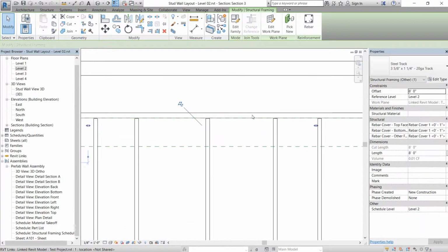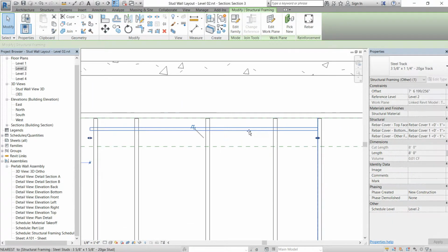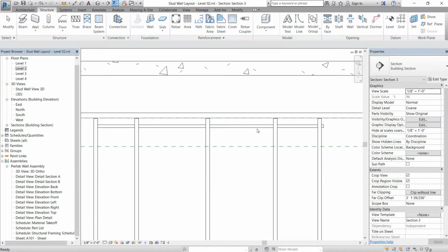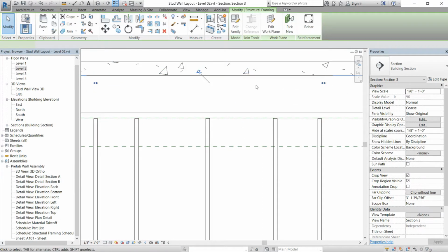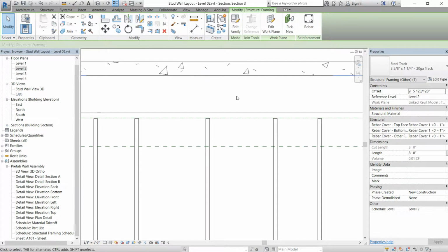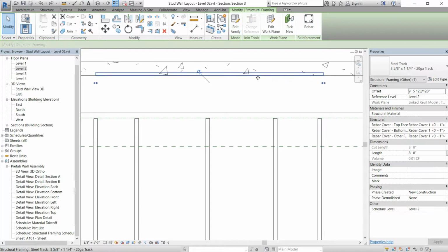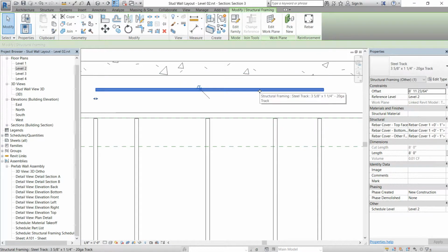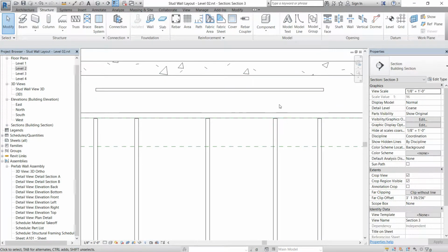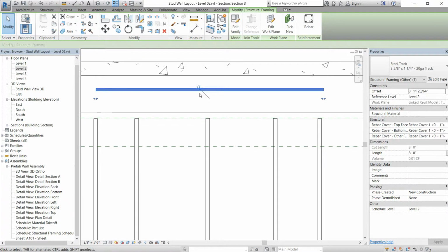That's actually pretty close to the height it's going to be at. So we'll just hit align. Actually, you know what? We'll have this go all the way up to the roof, and then we'll select it again and use this flip toggle. Should be there. There we go. Behind the wall, maybe. Weird.